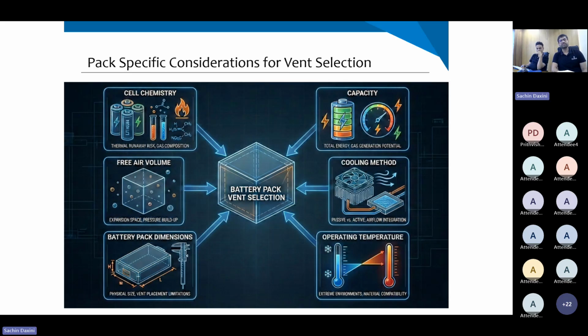If not, then a membrane burst system may also work for you, which is usually commercially lower cost, as well as very fast to roll out. We have to understand more about your pack to be able to answer. But usually high density NMC packs surely need a very high flow rate, and for those high flow rate applications, dual vents are more suitable.